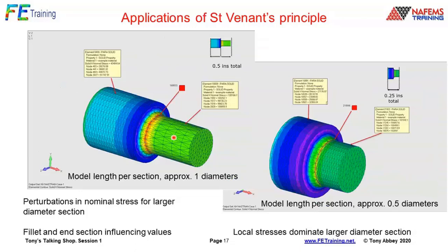So I can relate that back to the plate and everything else. We could do a real kind of study on the detail of the stresses in here. Come down to 1/2 a diameter, and I've really messed it up. The influence of the loading, you can see the patterning in here. The boundary condition here is dominating the stress diffusion. The assumptions or the limitations of the rigid element here, again, the same kind of idea. So basically, I've really disturbed the local stress variation because I'm not following the principles or the guidance of St. Venant's Principle.